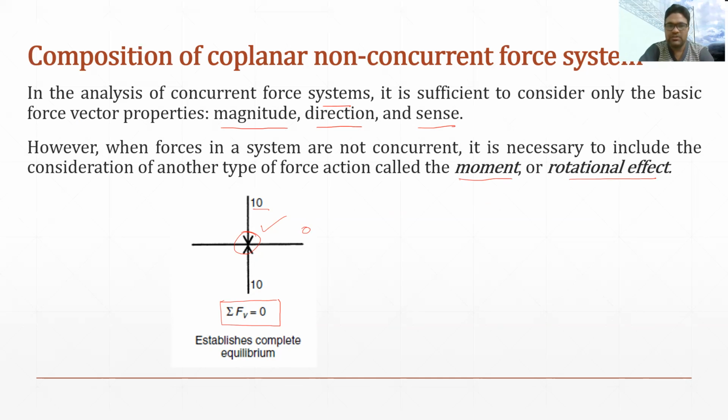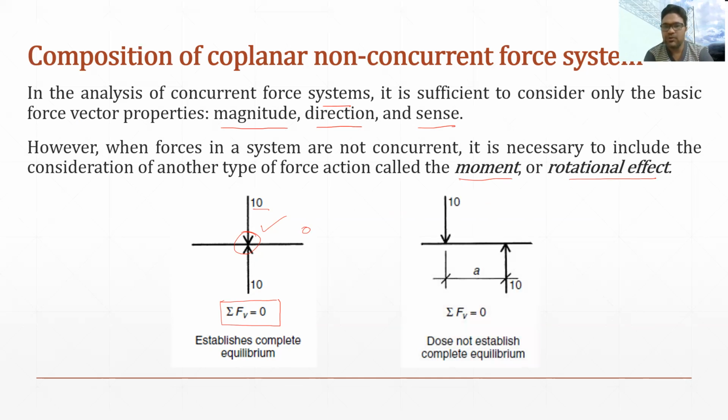Now I will show you the second figure, and in it you can see the same forces, with the same magnitude and the same sense, but the difference is they are not concurrent. They are not acting on a single point. In the non-concurrent system, they are acting on two different points and they have a distance a.